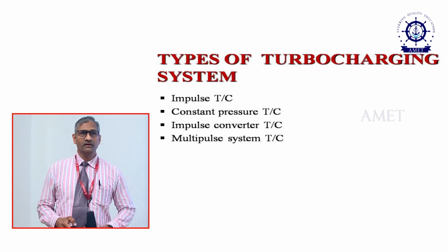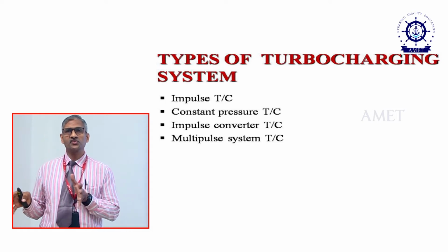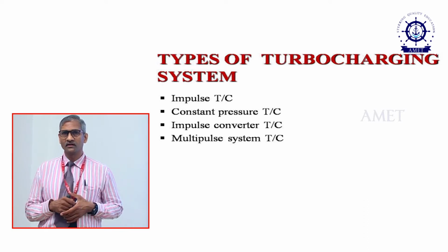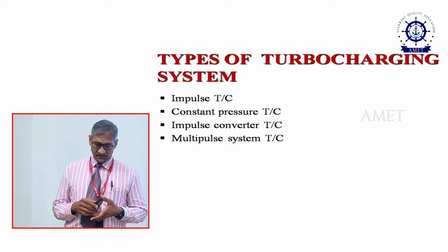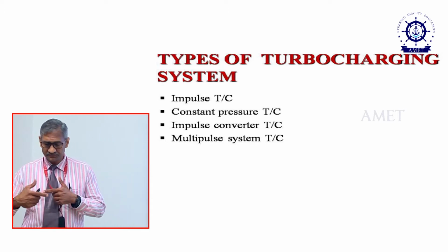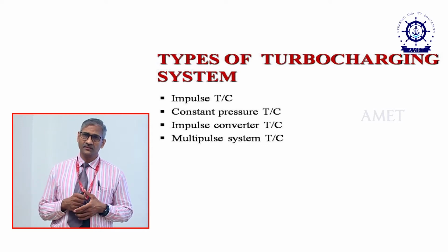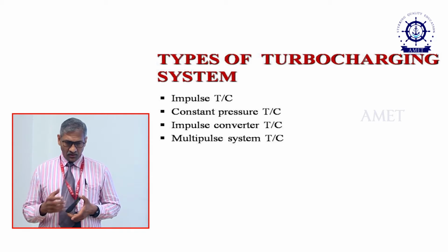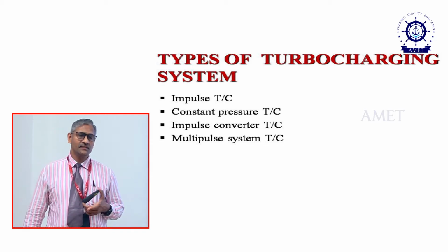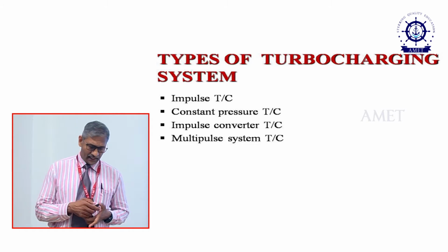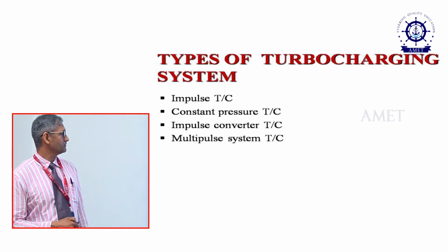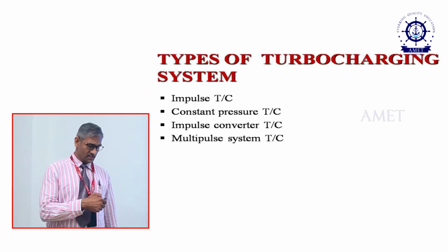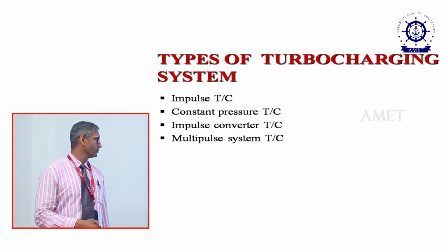Okay. Now, so far I spoke about everything related to the exhaust side. On the other side of the turbocharger you have the blower. Now, let us look at the scavenging side. The purpose of a gas turbine is to generate enough rotational energy so that the blower can run. That is the purpose of a turbine. Now let us look at how the engine is being supplied with air. Let us look at three systems that are available. Typically, scavenging arrangements are generally looked at in three formats. One is called reverse flow and the other one is called uniflow scavenging.